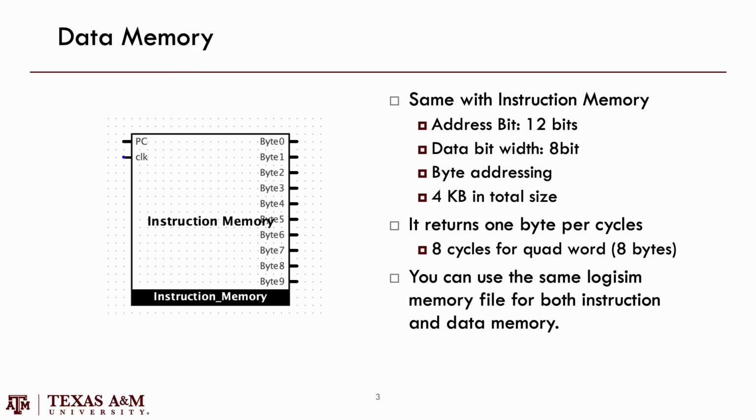For the data memory, it is almost the same configuration as the instruction memory, but it could be somewhat different in ways that I didn't mention in this tutorial. But as long as you make the same address width and data bit width as the instruction memory, it should be fine.